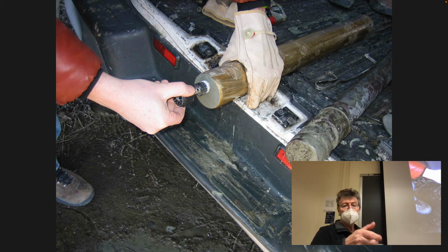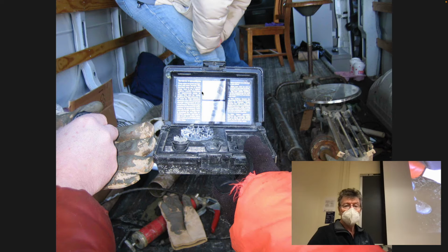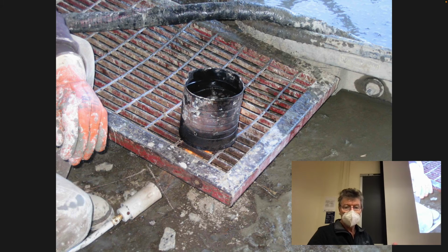When you exceed the torque, when you fail this little thing that the flats have been pushed into, when you fail it off so this round can actually move because it's exceeded the torque that you apply to it. The measurement of the torque that's recorded on this little dial here gives you some ballpark appreciation of the strength of this clay. Pretty rudimentary, but a quick and dirty way of doing this. So-called Torvane, Tor for torque.